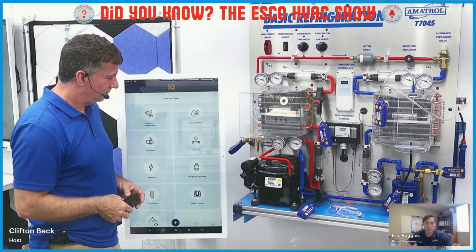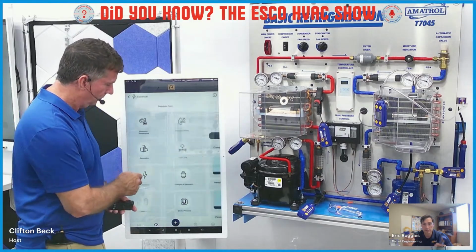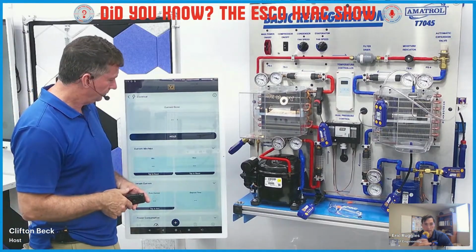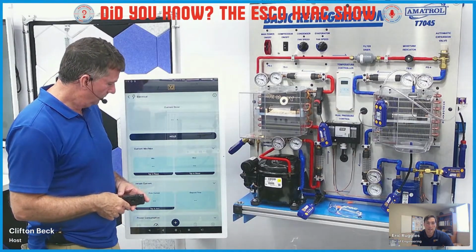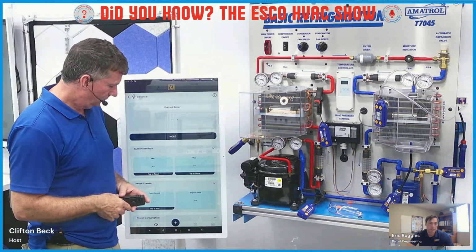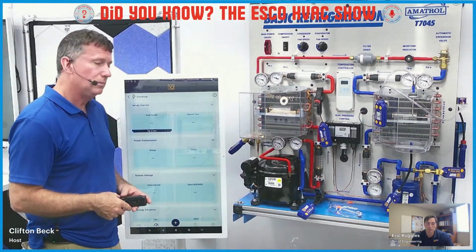Electrical session is with the amp clamp. If you click into that one, if you have this on a system, it'll show you basically what the amps are reading. It'll also show you an inrush, if the compressor jumps on, how high that is. It'll track your maximum and minimum values during the whole session. And you can take a snapshot of those values and add it to your report as well. So you can typically take a snapshot of the compressor, the condenser fan, the evap fan, and show what they're doing.